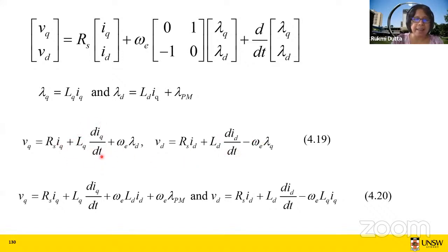They can still include the time variation of a DC quantity, like dIQ/dt, as an inductive drop, but it is no longer theta dependent, and it can handle dynamic conditions.